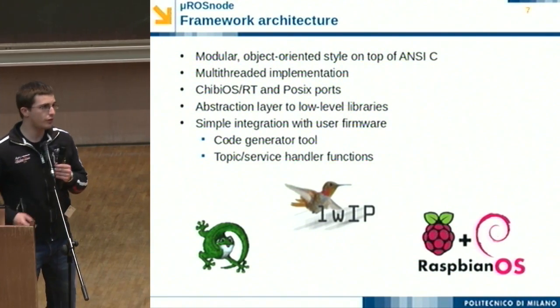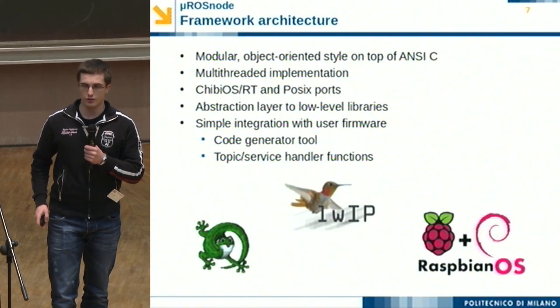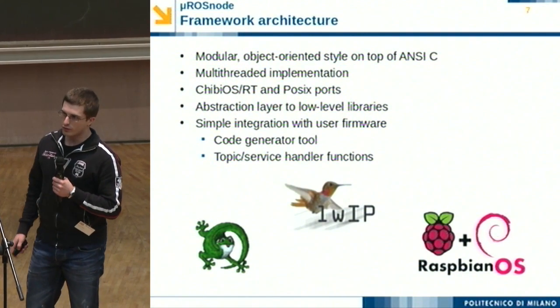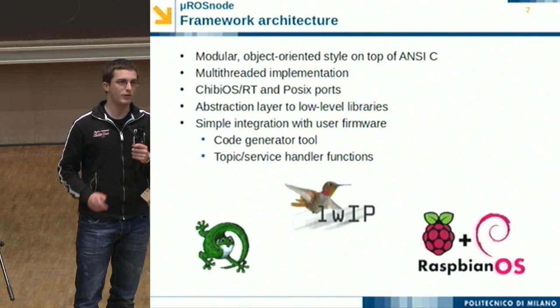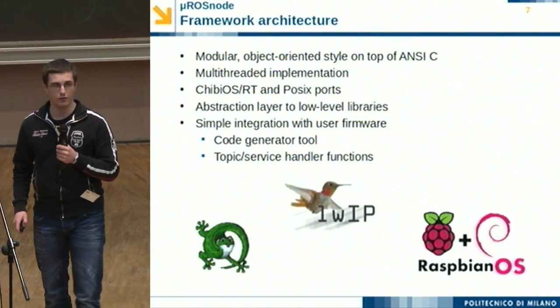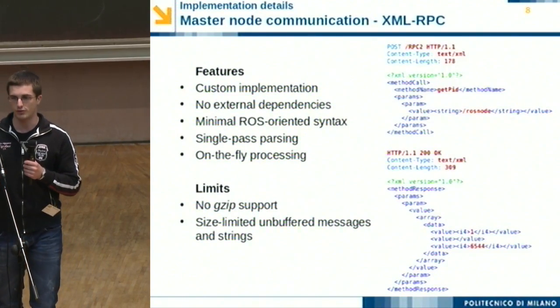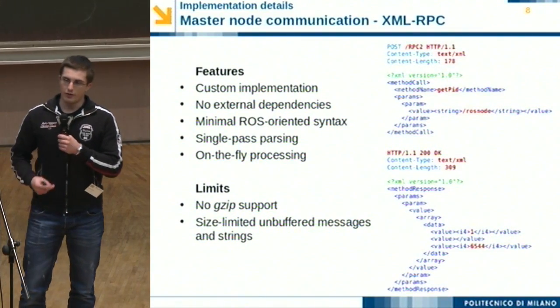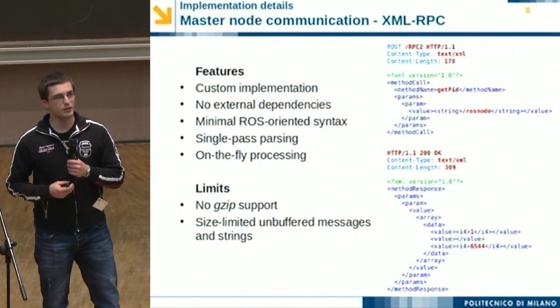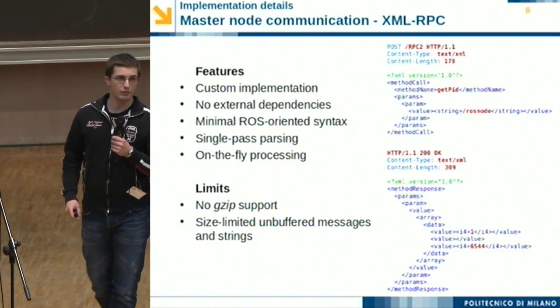The integration with the user firmware is assisted by the use of a code generator tool, and the user is typically required only to write the functions, the handlers for the topics and services, while the messages are automatically generated. By the way, I have a few notes about the XML RPC implementation, because there are some libraries outside